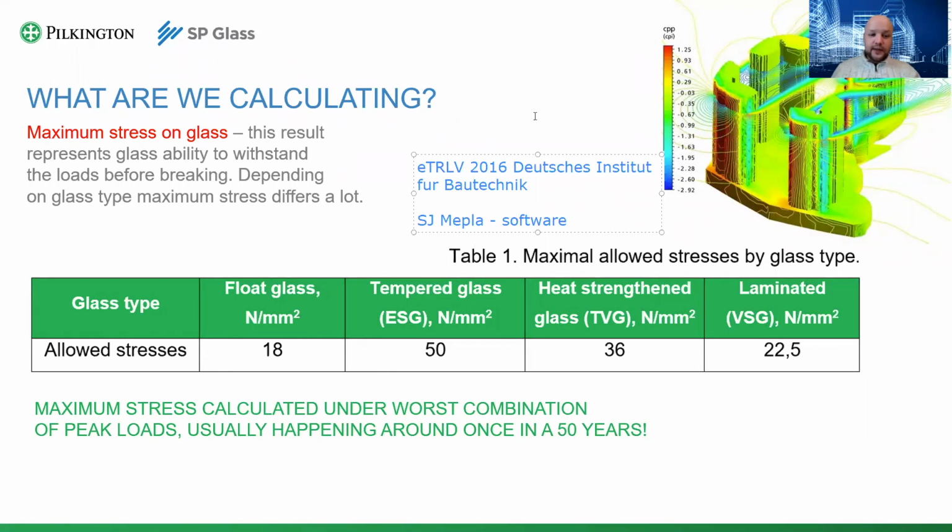Do these numbers vary with different thickness of glass? No, they don't. The next question would be why? Because these are very interesting numbers. They are derived not only from the stress which the surface of the glass may withstand, but also take into account a little bit of the glass edges, which are rather important. And of course, thermal treatment changes the surface parameters and the surface stress. This is mainly the surface stress which the glass can withstand, and that is why it makes no difference what the glass thickness is.